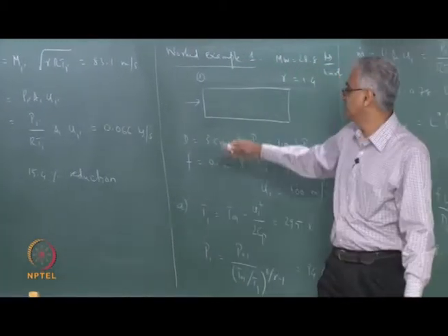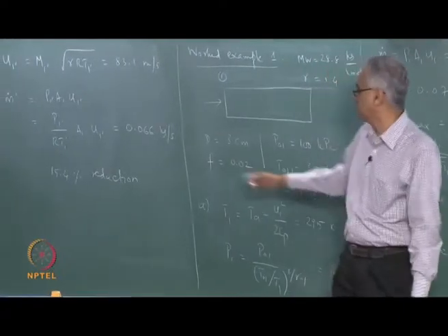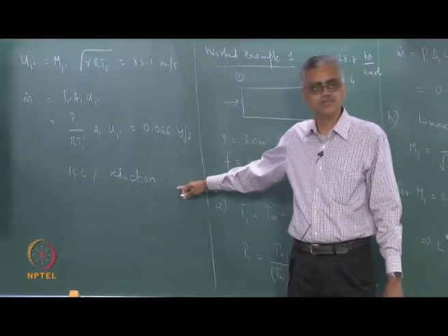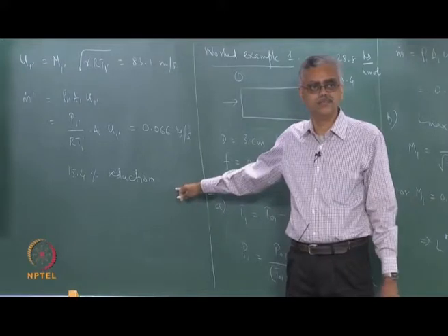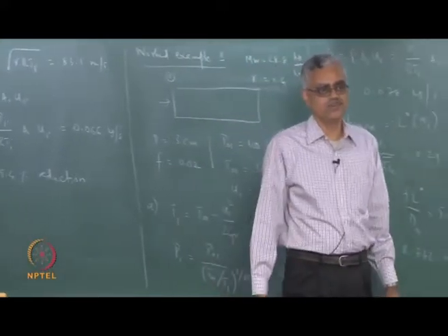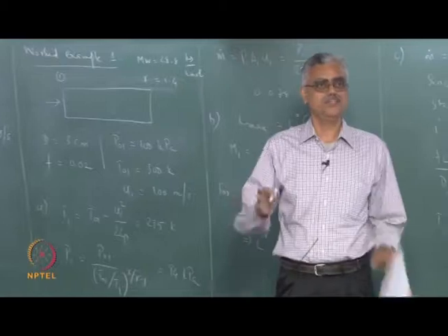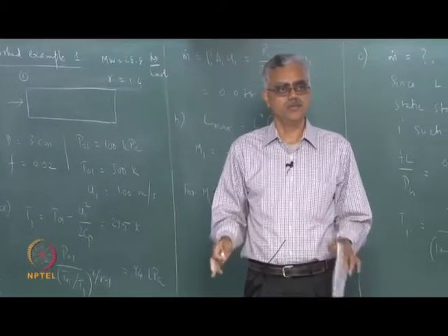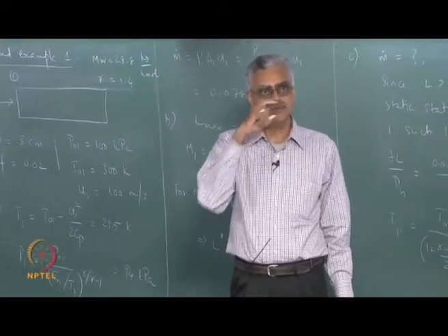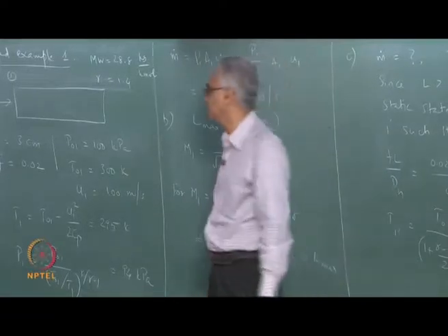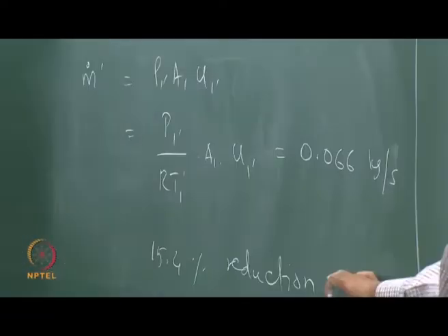Notice that at the exit state now, if you are using a 15 meter long pipe, the exit state Mach number is 1, okay, whereas you might have designed the equipment for some other inlet Mach number, which is connected to the end of the pipe. You may be expecting some Mach number and some mass flow rate, whereas the conditions are totally changed now.